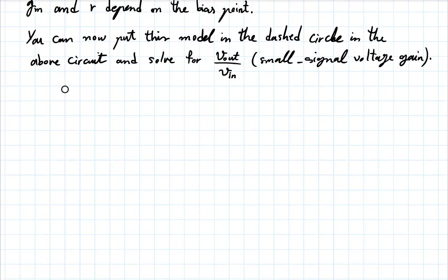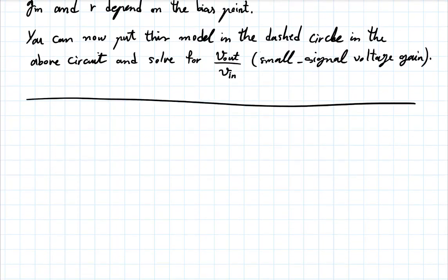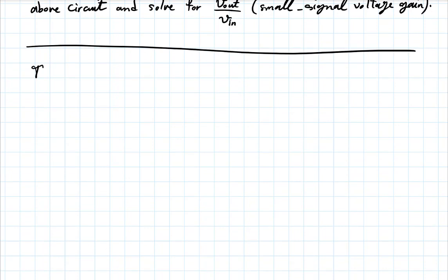I'd like to close by making one other statement. Like I said in the beginning, all of the same approach applies if you're dealing with MOSFETs. It's just that the model for the transistor itself is a little different. The same approach, meaning separating the DC bias and then adding the small signal on top of that, applies when you have MOSFETs.